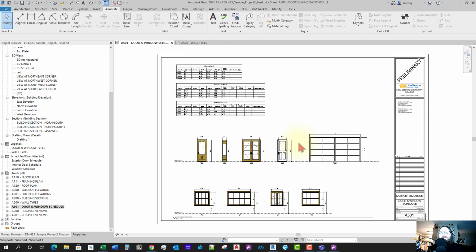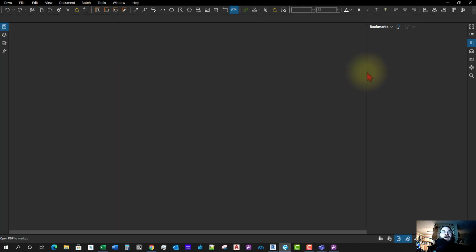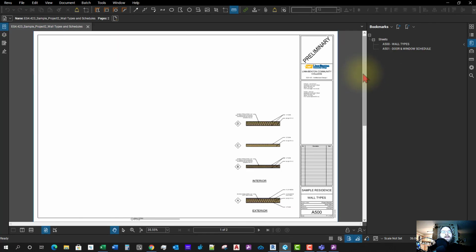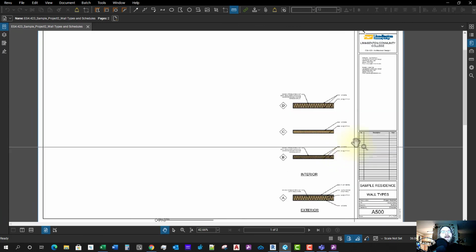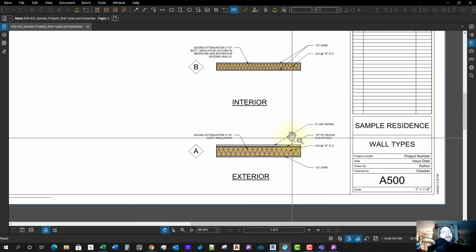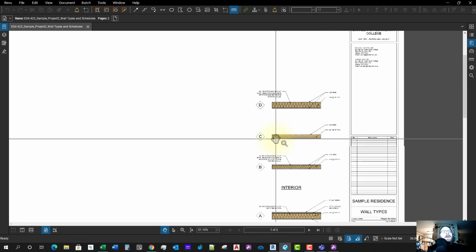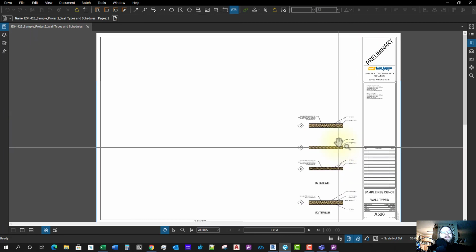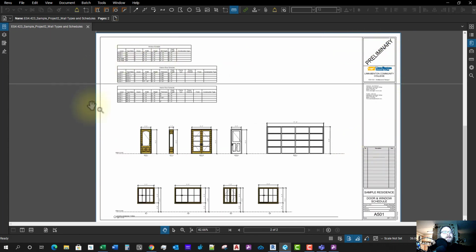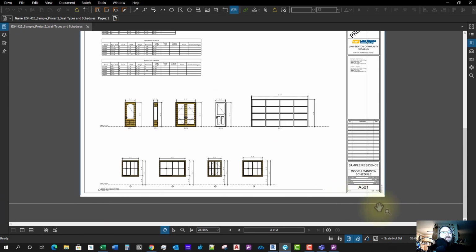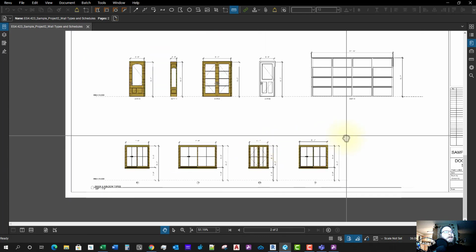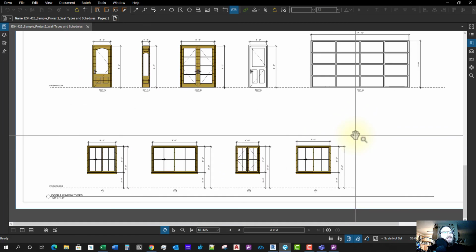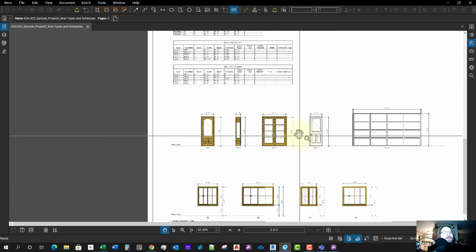Now it'll be good to open up the PDF. It should be default to open automatically. But before you ever turn anything in, and before you give anything to your boss or clients, always good to open it up, look, and make sure that it's actually readable and that everything you have is on there. It's to scale. That it's the right sheet size. That'll tell you that at the bottom on Bluebeam. And just take a quick gander at it and just make sure that it looks like it's supposed to.